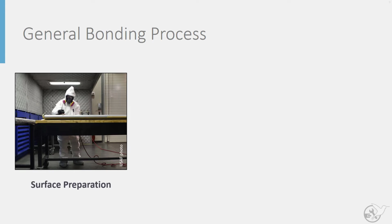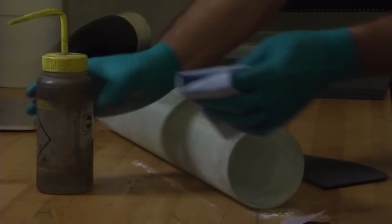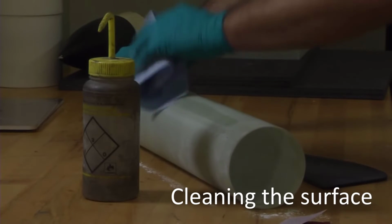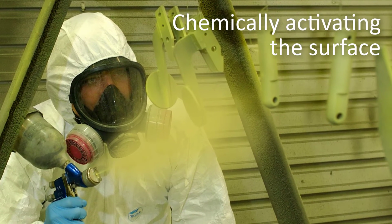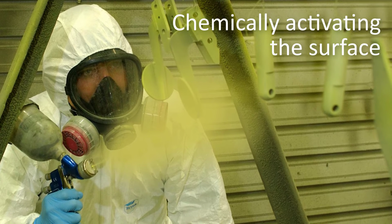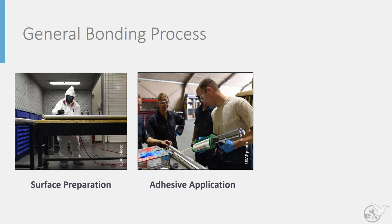It is important to understand the basic steps within the bonding process in order to understand the potential risks for adhesion failure in a bonded joint. If we start with the two parts to be joined, the first critical step is to prepare the surfaces of the parts. This surface preparation step can involve one or more of the following: increasing the roughness of the surface using an abrasive material such as sandblasting, cleaning the surface using industrial solvents to remove any grease or impurities, and using a chemical process to activate the surface of the part, making it more prone to form chemical bonds with the adhesive material.